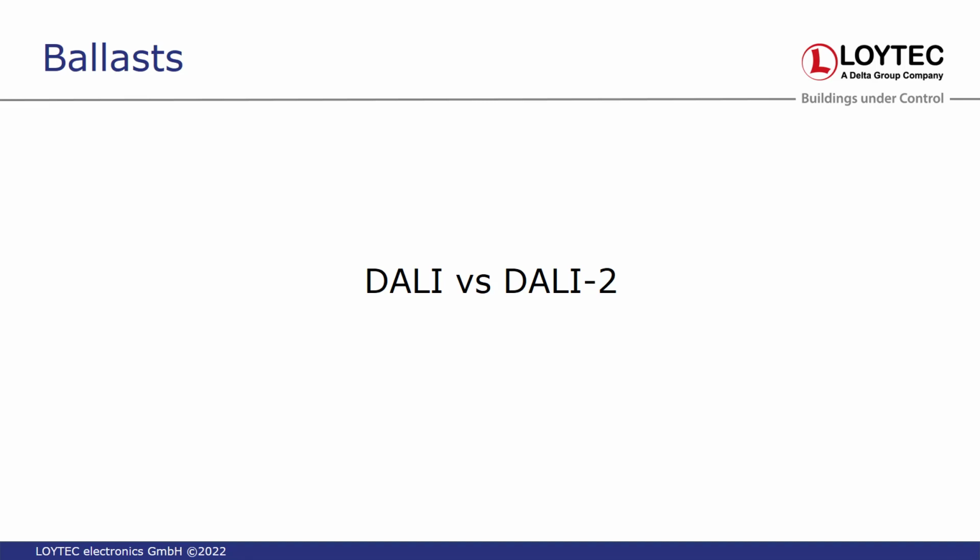So it's still true, but what you say doesn't mean that it does not work. But when you have a mixed setup between DALI 2 sensors and ballasts, it's not a bad idea to have ballasts that are really DALI 2 certified, just to make sure.